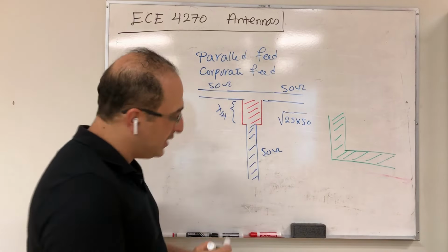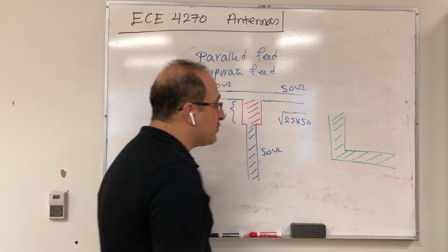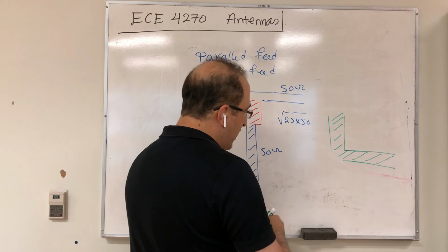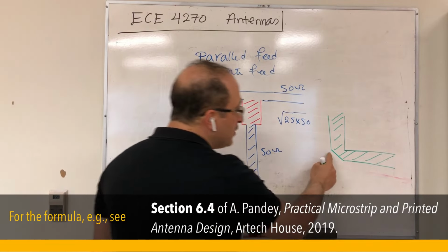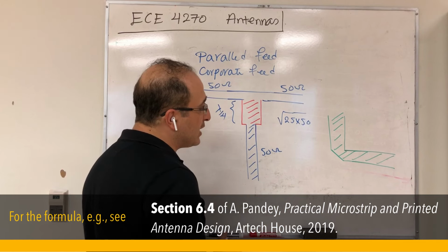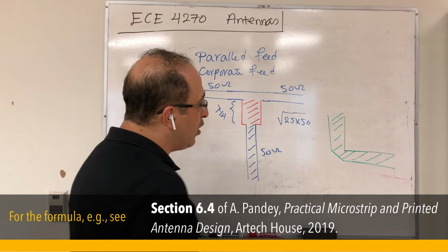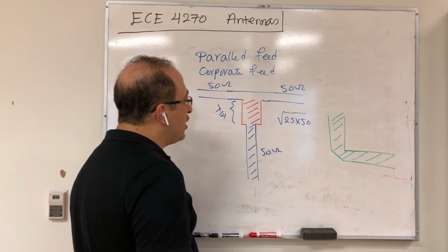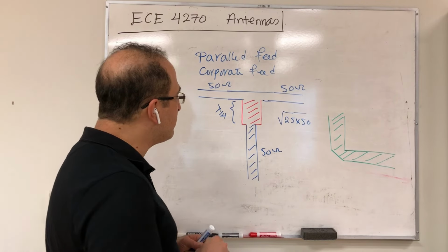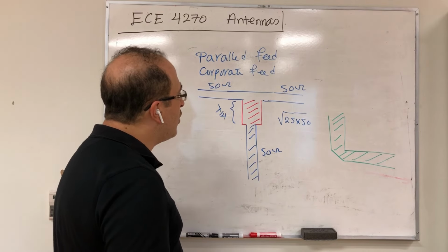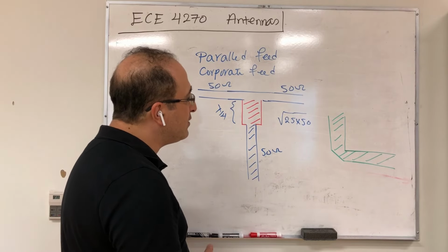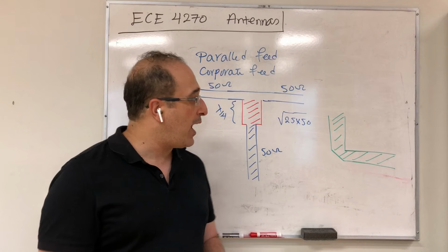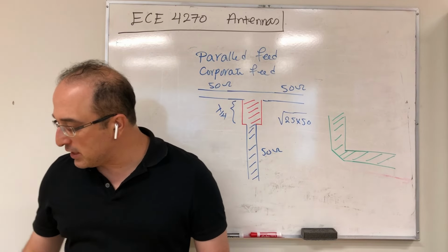But if you do it like that, then there could be some problem with the characteristic impedance because of this bend. So one way to handle this is essentially to miter this transmission line and have it in this form. How much you need to do that are all also design parameters, and there are formulas for that. But essentially this shows a structure where you use this type of bend to change the direction of your transmission line by 90 degrees. So these are essentially the three main components of this parallel feed that we have. We have our transmission line, we have our power divider with quarter wavelength transformer, we have our bend, and of course these are going to go to our patch antennas and feed them. So that's the introduction to this parallel feed that we have.